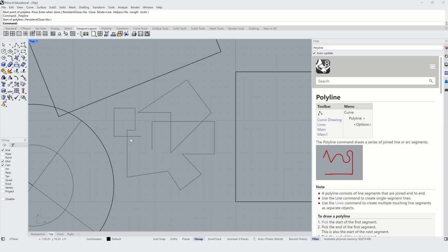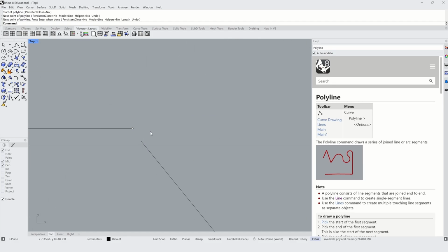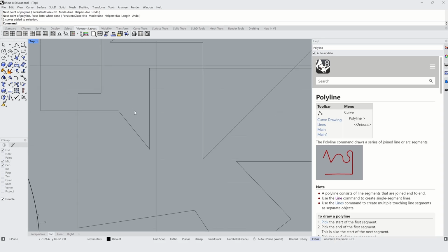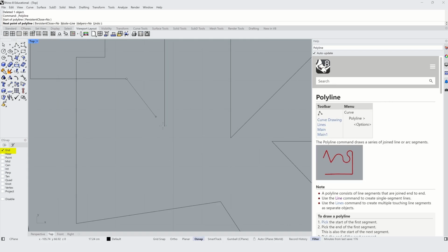modeling precisely. For example, I left this polyline unfinished if I wanted to have it as a closed shape. Without the OSnap, I could kind of draw a line segment like this. But if I zoom in, you can see that they don't actually meet. This could cause a problem for laser cutting, or if you're printing at a larger size and that gap becomes visible on the page. With OSnap turned on, and particularly with endpoints selected, let's turn everything off and just pick endpoint, and see that it immediately jumps to that endpoint.